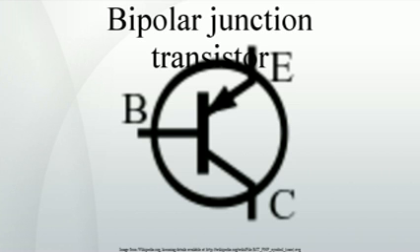The base is physically located between the emitter and the collector and is made from lightly doped, high-resistivity material. The collector surrounds the emitter region, making it almost impossible for the electrons injected into the base region to escape without being collected, thus making the resulting value of α very close to unity, and so giving the transistor a large β. A cross-section view of a BJT indicates that the collector-base junction has a much larger area than the emitter-base junction.